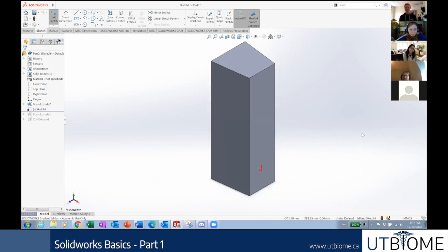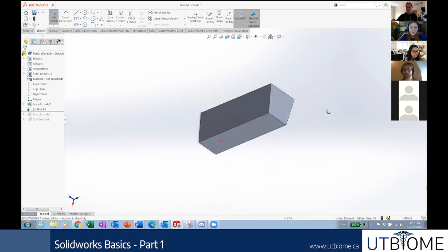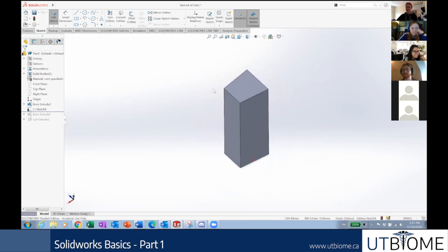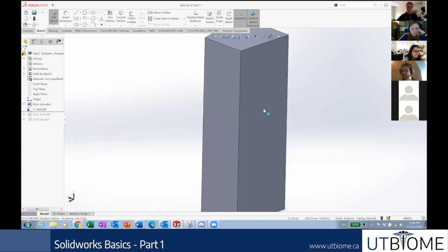I'm also going to explain some basic controls in SolidWorks real quick, because I've been moving stuff and you're going to get in here and be like, how does this man look around? In order to look around, you actually use your scroll wheel as a button. This is why it's important to have a mouse, because if you were using your touchpad, I don't know how you'd ever SolidWorks. I'm going to click my scroll wheel, and when I click it and hold it down, it lets me do whatever this motion is called. We're going to call it look around. I can look around while I hold down and move it. You also use the scroll wheel to zoom in and out. If I push the scroll wheel forward, we zoom out. If I pull the scroll wheel towards me, I zoom in.